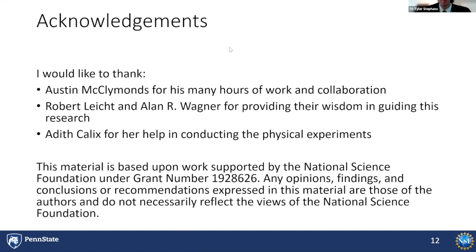Why the Jetson Nano was used. So the camera that we were using to collect the images is called a ZED 2i camera from Stereolabs. To use it, it requires a computer with an NVIDIA GPU that supports CUDA. And so that's why we use the Jetson Nano, so that we could use this camera. This camera has stereo capabilities that we did not use, but it is pre-calibrated, so we didn't have to perform any sort of calibration on it either. That's why we use the Jetson Nano, so that we could use the camera we had.